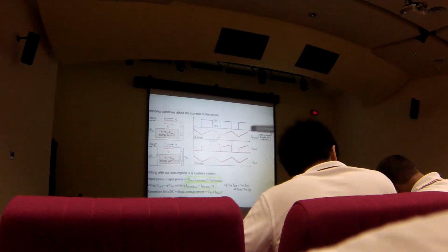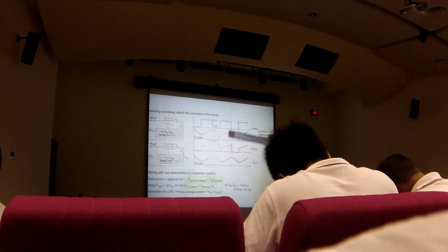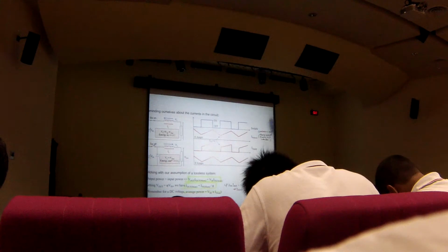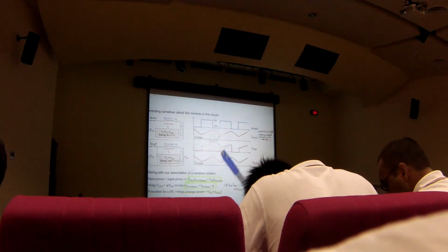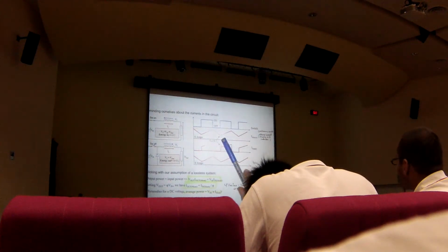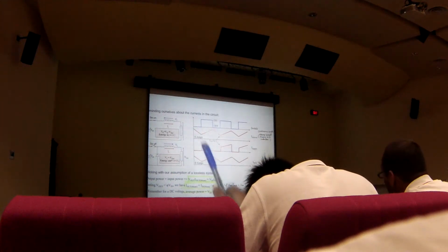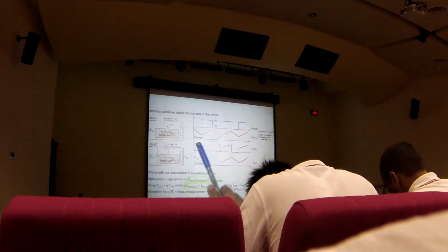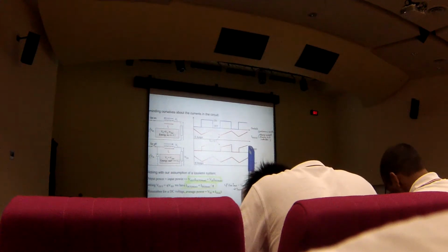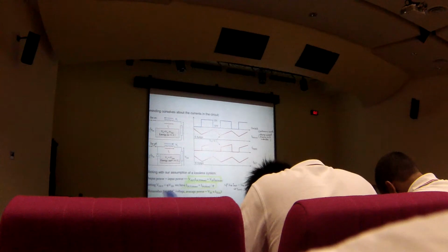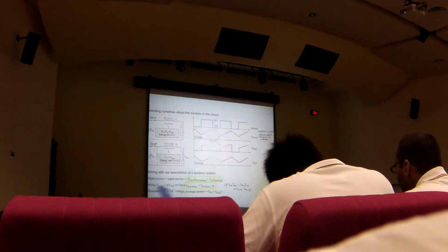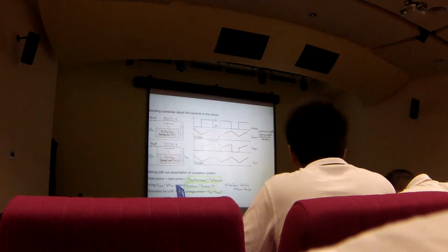The same waveform. Just see that I on for the supply is equal to the current through the inductor. This is always in continuous mode because it's always floating above 0 ampere. There's always current in the inductor. So, if you stick with the assumption of a lossless system, the output power is equal to your input power. There's no power loss.